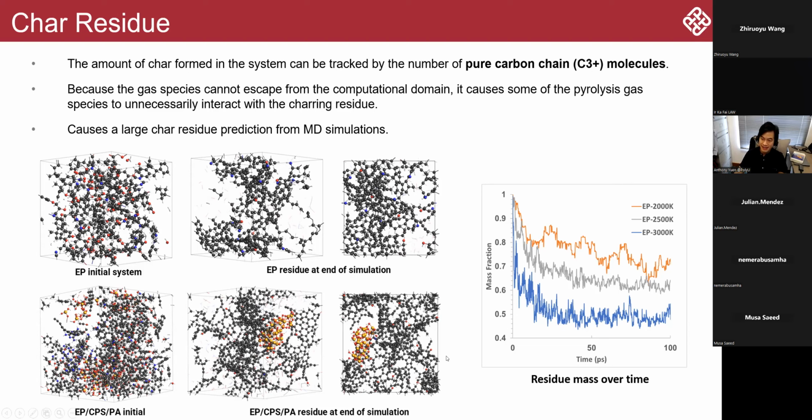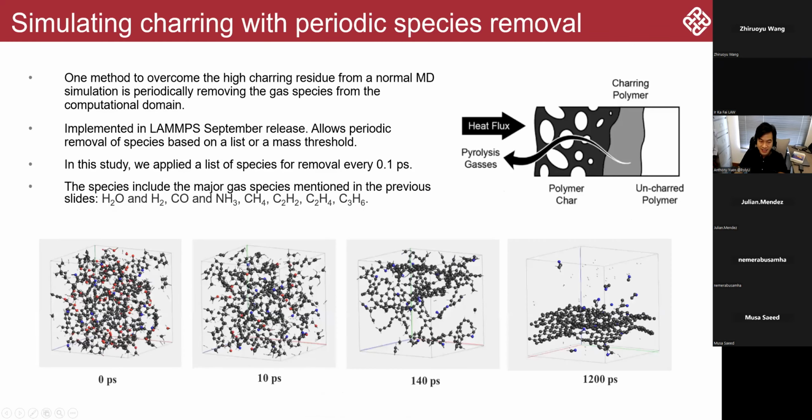So looking at the residue, we can look more clearly at how this activated carbon works in the polymer matrix system. If you benchmark the two breakdown processes, not only does the flame retardant play a role in protecting the polymer itself, at the end of the day the activated carbon will also contribute a lot to the char formation. So here is another intuitive method to look into char layer formation.